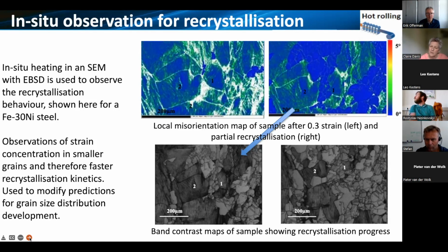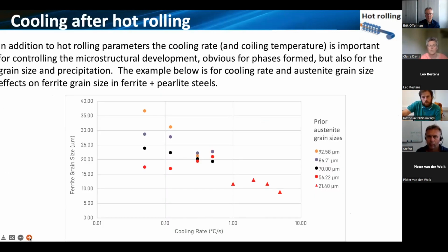And then we can see through the formation of the recrystallized grains, so these are taken up, heated, held for a little bit of time, and then with EBSD you can follow the recrystallization process and the recrystallization happening in the highly strained areas. Again, not a surprise. But it illustrates to us the importance of your starting grain size distribution, not just the mode grain size, particularly when we start to get skewed distributions. So these more complex steels where we might not have a very tight unimodal grain size distribution. So really important to understanding principles of what's going on as well as some of the data.